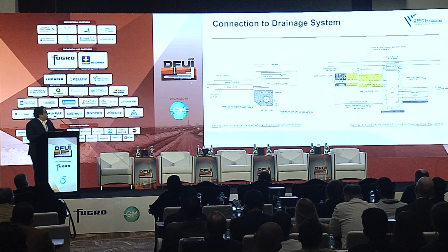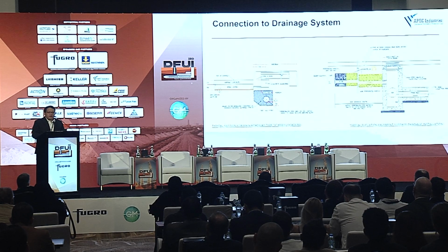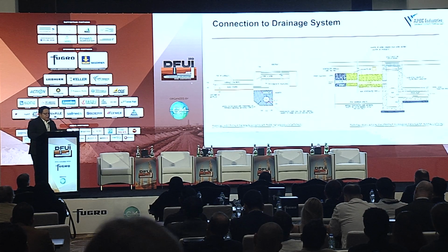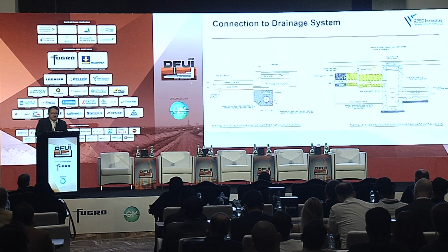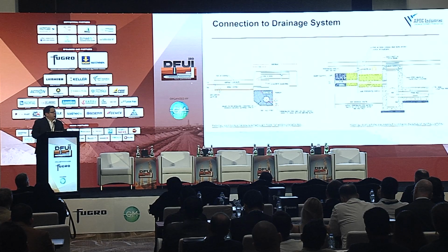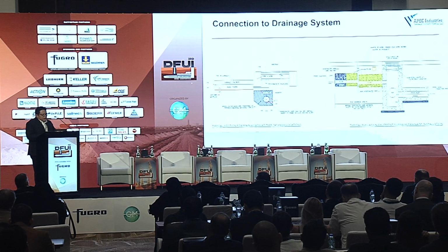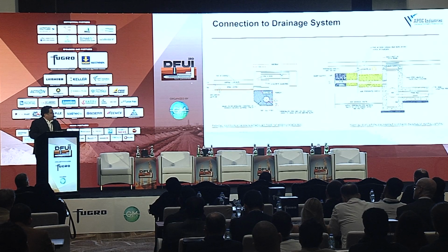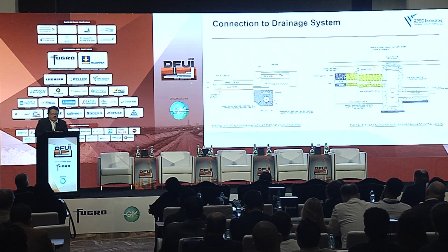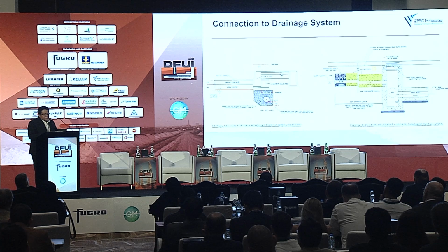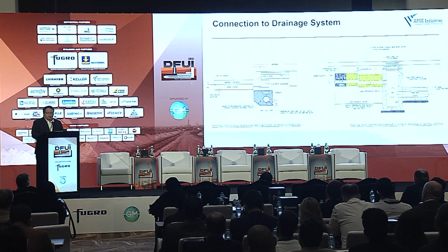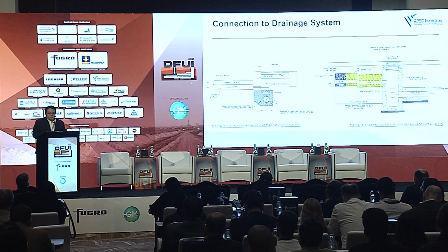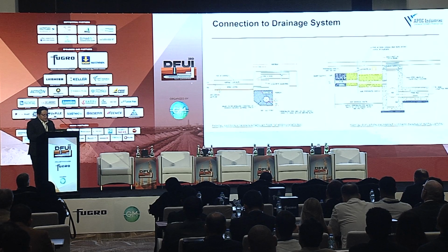This drainage geocomposite still needs to be properly connected to a drainage system. So the collection should be on the edge drain or a collection pipe. There are proper requirements for the installation of these drainage geocomposites, as failures may include clogged headwalls, crushed pipes, and poor outlet detailing. Therefore, installation quality and construction supervision are equally important as the product selection itself.